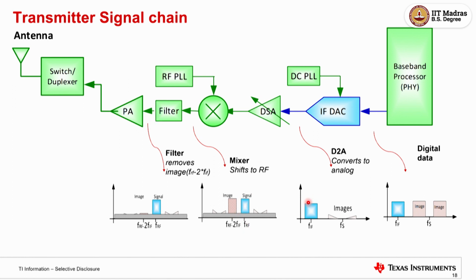So the challenge in a filter is, at 2 gigahertz, it has to quickly filter anything which is 2 megahertz away. That's the challenge in any filter. If you want the cutting part, how far away you want to cut at that frequency, it's a relative portion. If you want to cut a frequency which is very close as a fraction of your center frequency, the filter gets very complicated in size.